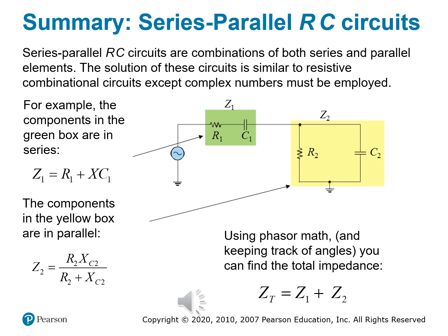The next thing is we have to combine those two. Once you've calculated both impedances, Z1 and Z2, for both of those boxes, you can simply add them together, where Z total equals Z1 plus Z2. But don't forget that you're working with phasors here, not just magnitudes. That means keep the angles in play, convert to rectangular or polar form as needed depending on the math you need to be doing, and be cautious with the signs and the quadrant placements. This is where all the training from the earlier modules pays off.